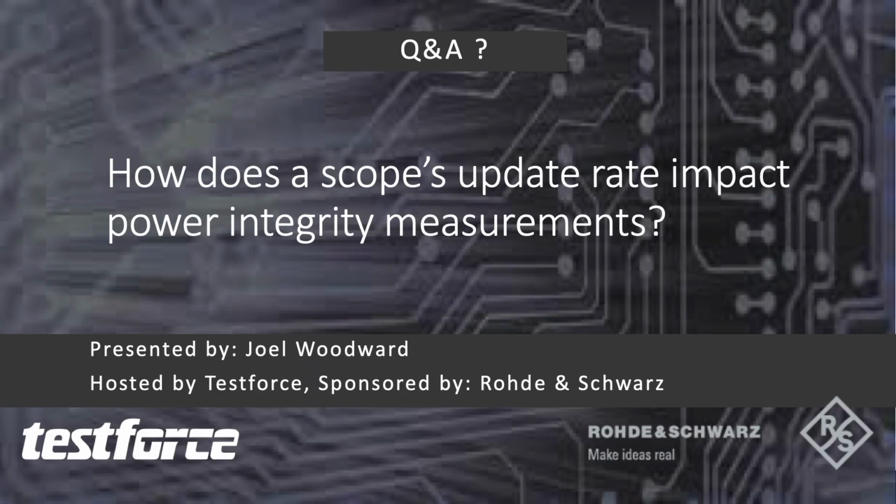I have one last question, and that is, how does the scope's update rate impact power integrity measurements? When people talk about update rate for oscilloscopes, it has to do with the scope's ability to acquire, process, and display acquisitions. Every time it does this, we'll call it 1 acquisition per second. If a scope can do that 100 times a second, then it would have an update rate of 100 acquisitions per second. If it can do it 100,000 times a second, it would have an acquisition rate of 100,000 times per second.